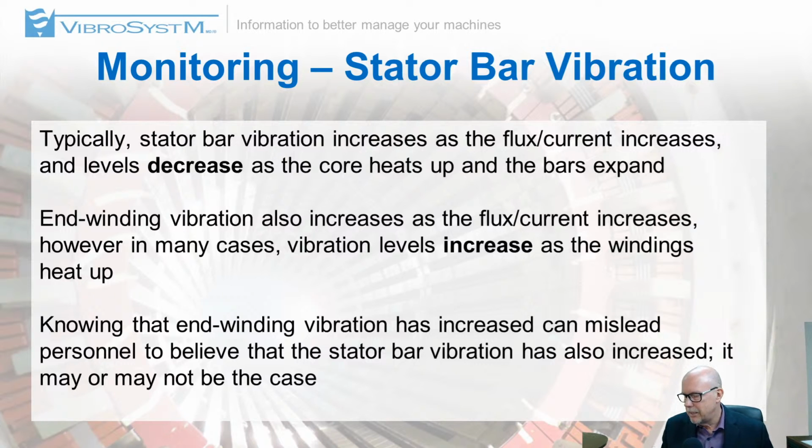So what I mean by that is some people believe, well, if the end windings are vibrating a lot, the stator bar vibration is high as well. Sometimes it is, sometimes it isn't. It depends exactly how the unit is performing under which operating condition.